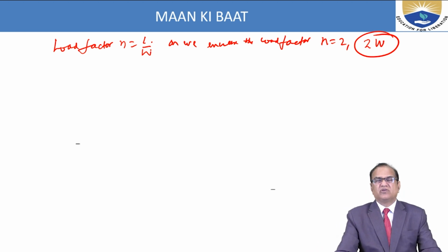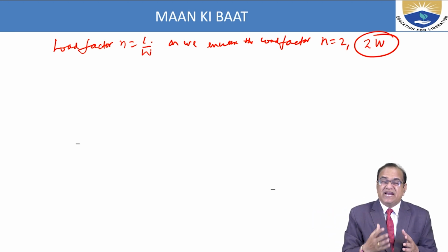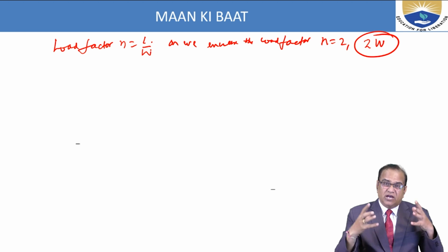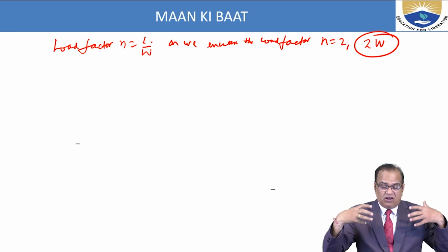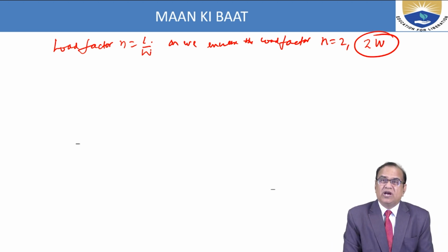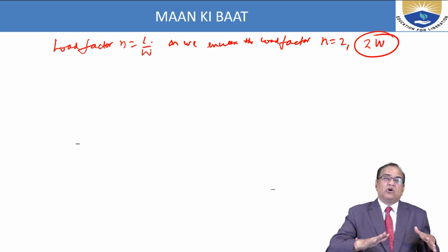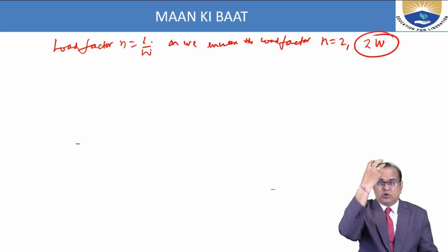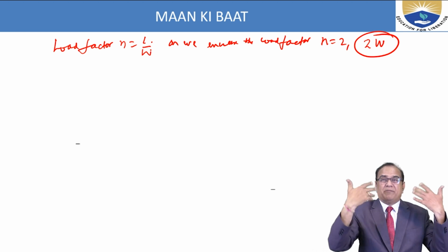Also, if you are climbing or pulling up, the pilot who is flying, or the passengers, will feel a lot of trouble. A human can sustain only up to load factor 6. As the load factor increases beyond 6, if you are going up for the pull up, your blood will come down, and if you are coming down, your blood will go up.